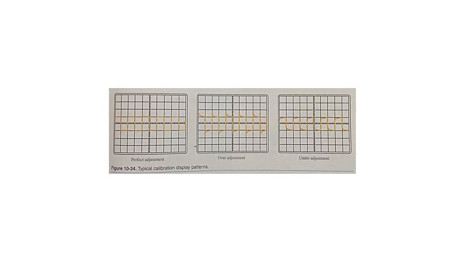Additional features. Today, many oscilloscopes in use are completely digital and incorporate a computer as a part of the scope system. The wave pattern can be observed as well as saved to a battery-powered computer memory. Many scopes are also equipped with print-to-paper capability to copy the wave form pattern. Some scopes used today are a combination of VOM and oscilloscope with a display screen. The display screen will not only display the wave pattern but also digitally display the frequency and voltage values.